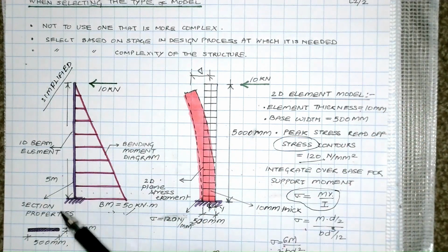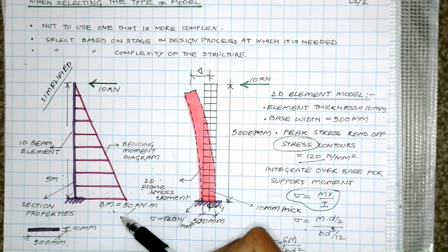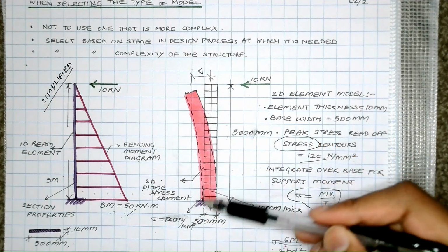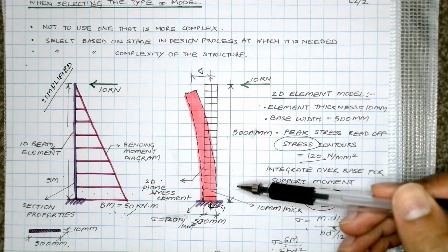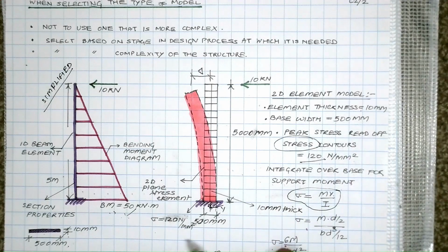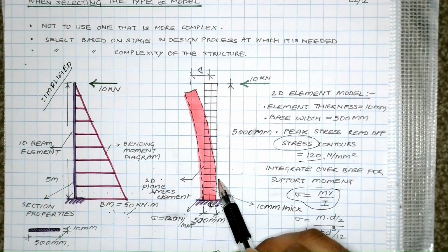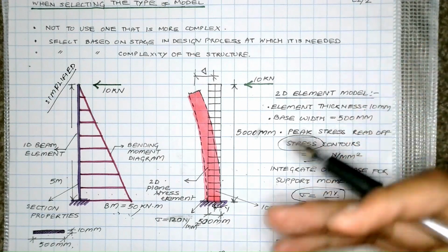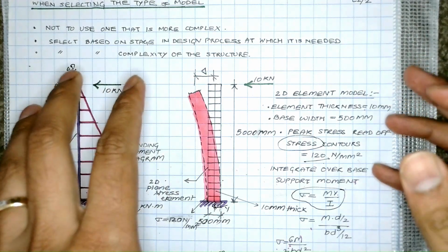There are different advantages of both cases. One is simplified: you get the bending moments, which is something you really need. If you really want to know the stress profile in that plate, and you might need that for your connections or something else, then it's good to know the stresses. So it's good to model as a plate element or 3D elements if you are looking for stresses. It depends on how you want to model.